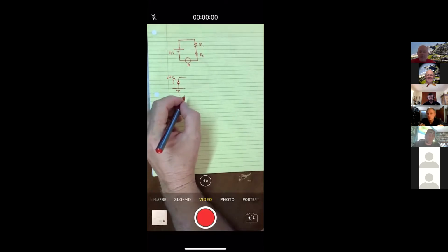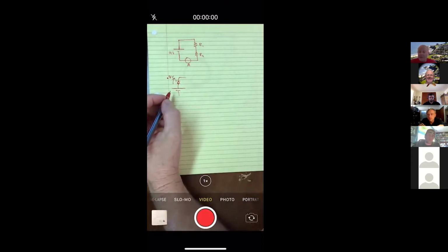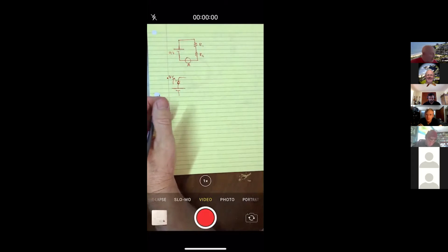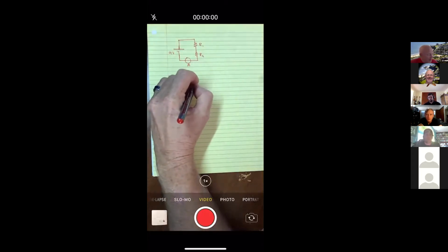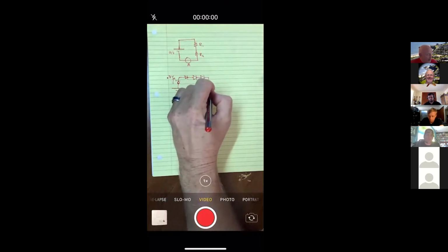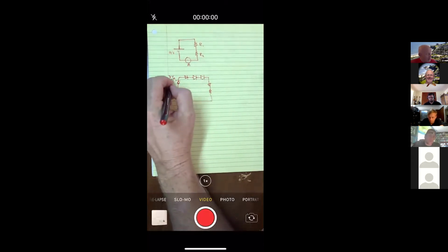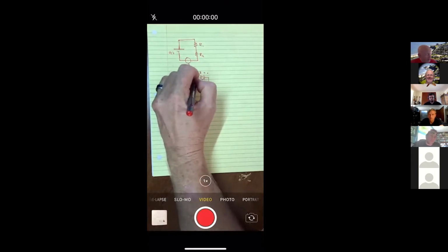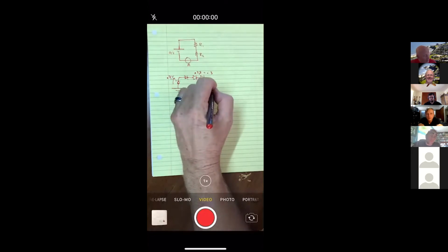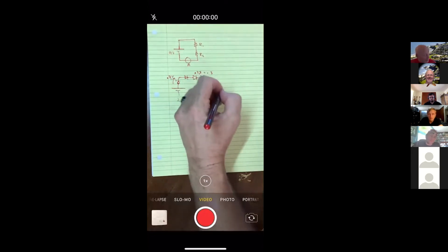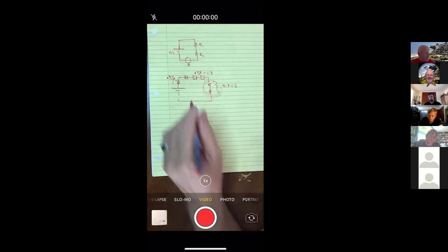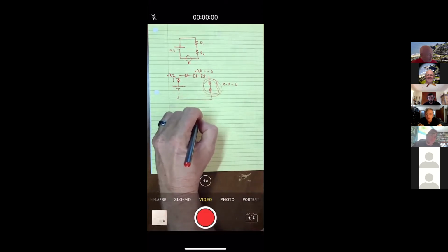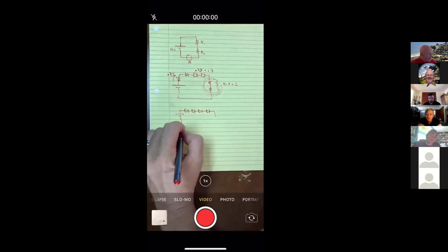So let's say I want to build a circuit that is not 9 volts. Let's say I want to build it at, say, 5 volts. Okay, or let me do 6. 6 would be a good number, because if I put 4 of these diodes in series and then ran it through my resistors, I would lose 0.7 times 4, that's 2.8, which is pretty close to 3. So by the time my voltage gets to my circuit, I have lost 3 volts. So 9 minus 3 is 6. So I can now build and work with a power supply. And so here's how I would build a 6 volt power supply. Ta-da!